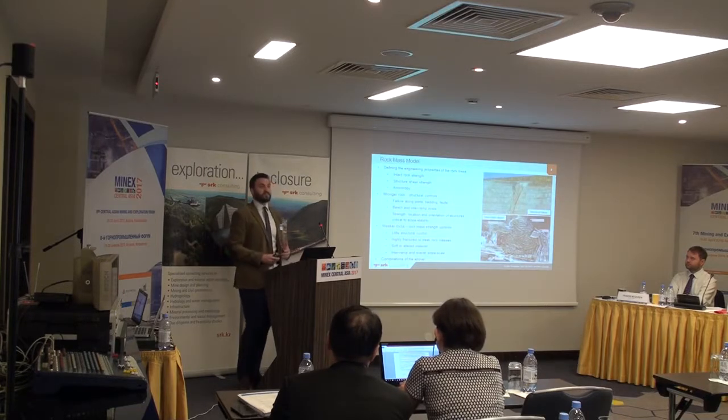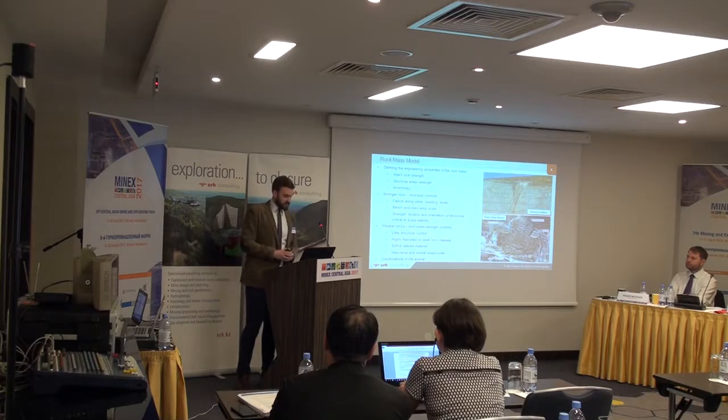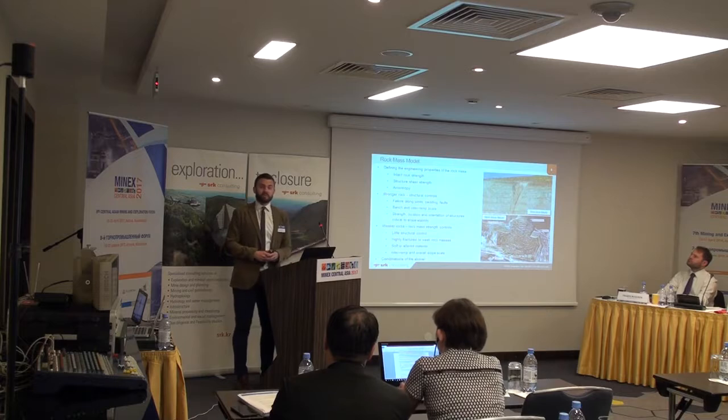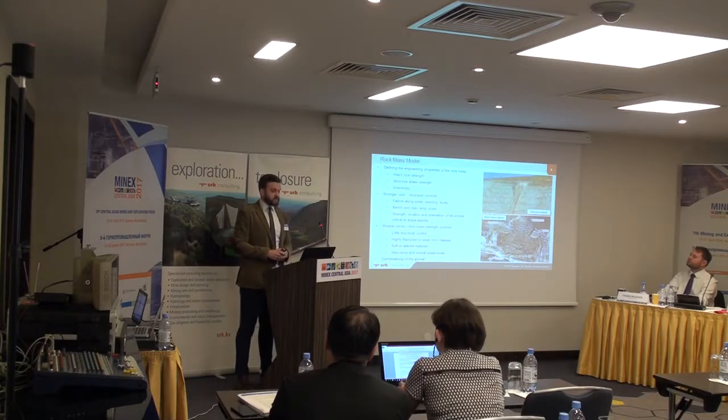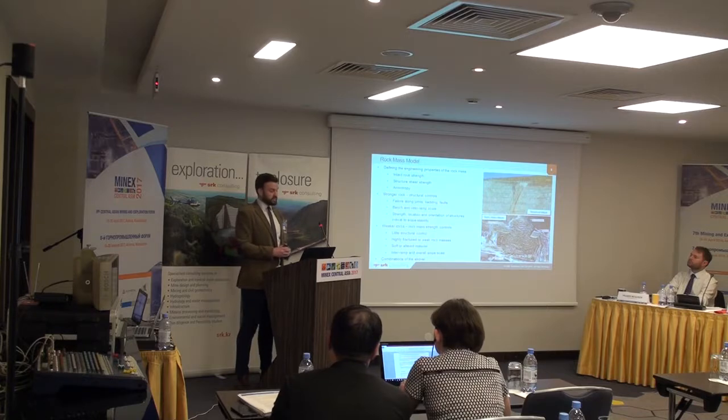So I'm just going to talk you through what we see as a rock mass model constitutes, then the geological model and the major structure model, and then a bit more on the hydrogeological model. And really that rock mass model should define the engineering properties of the rock mass. So you're considering the intact rock strength, the rock mass ratings, the shear strength of the rock mass, and how it's going to behave from an engineering perspective.